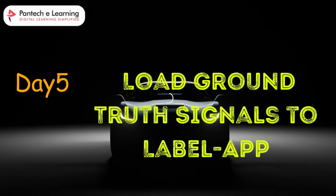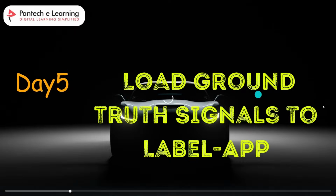Next, we are going to label the frames. Go through each picture in the video and each snapshot in the LiDAR data also. When you see something, mark it with the right label. For example, if you see a car, use a car label. If you see a brake light, use a brake light label. This helps you identify and keep track of different things in your data, which is very important for understanding it better and making the software smarter about what it sees. And this is all about tomorrow's session, day 5, load the ground truth signals to the labeler app.